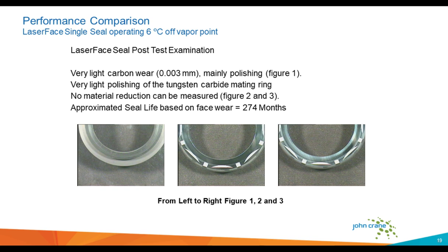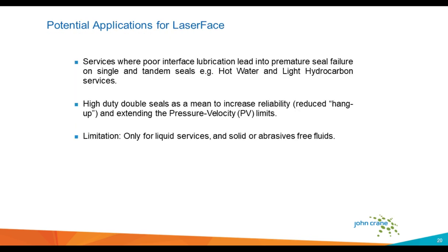In the laser face post-test examination, we noticed very light carbon wear, about 0.003 millimeters, almost negligible, mainly polishing. There was very light polishing of the tungsten carbide mating ring. No material reduction can be measured on both, so approximate seal life based on face wear was 274 months.